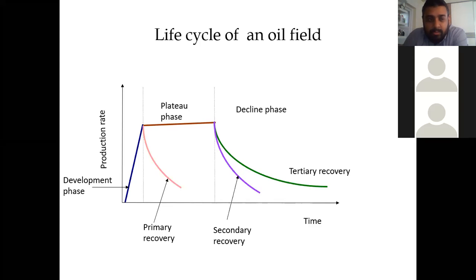That oil they send through trucks to other places, to the refineries. But anyway, they are sending 30,000 barrels, and their pressures are very nice, very high. Their initial pressure was around 5,000 PSI. Their bottom hole running pressure was around 3,700 PSI. Very nice pressure. They could extend this 30,000 barrels to maybe 100,000 barrels. They can do it. They were drilling more wells.